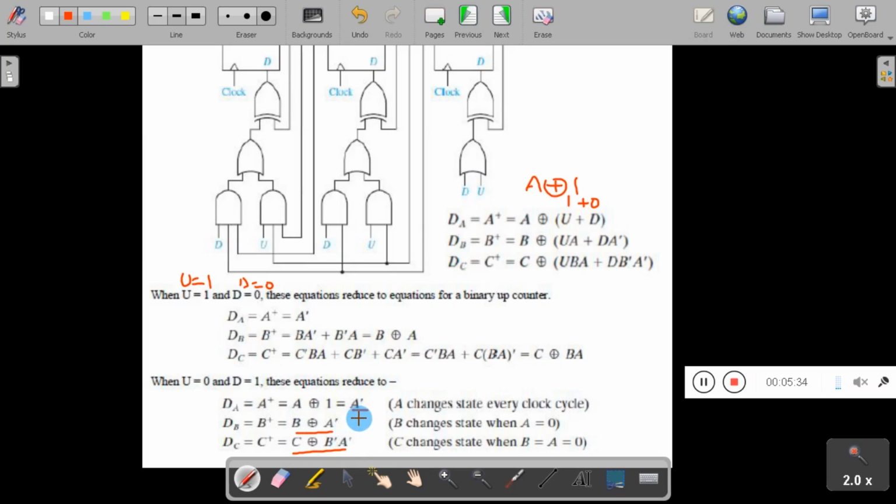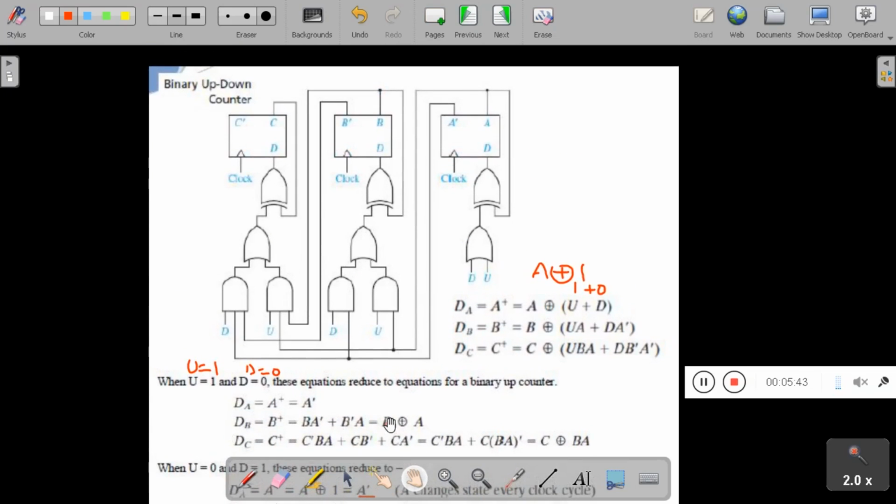Now you have to represent this in the design. So for design purpose, I have taken here 3 flip-flops. The first one is A, the second one is B, and the third one is C. All the flip-flops are driven by the same clock. Here it is represented separately, but it is connected to a single clock. Other than that, we have inputs DA, DB, and DC.